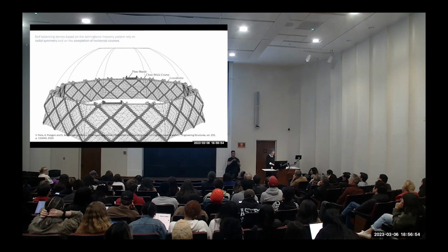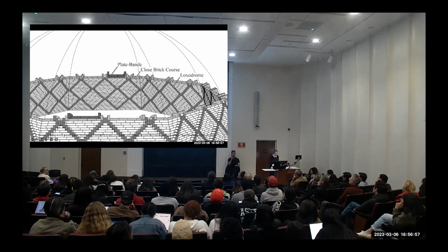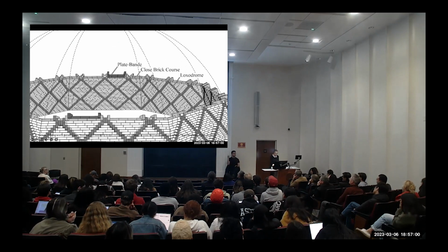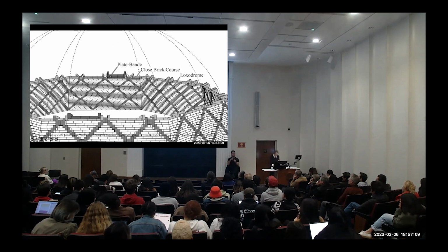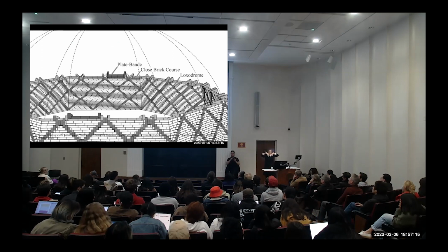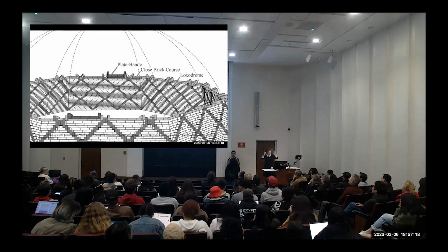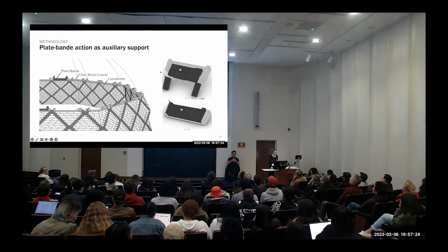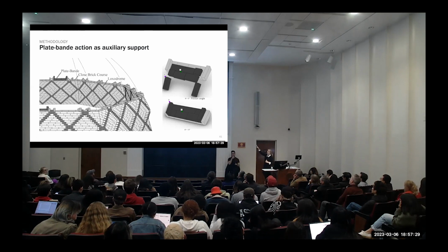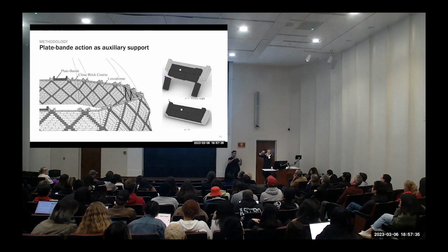And what happens then is very interesting. These herringbone bricks, these dark gray bricks, are stuck vertically like this. When the mason puts down the bricks here, they want to start sliding inwards, but then they collide with these vertical bricks, a bit like book stands, and they jump against that, and then the dome slides inwards. What you see now on the right-hand side is still from discrete element modeling. We basically make models by putting in all these bricks and then doing analysis, putting in another brick, doing analysis, and another brick, and doing analysis.